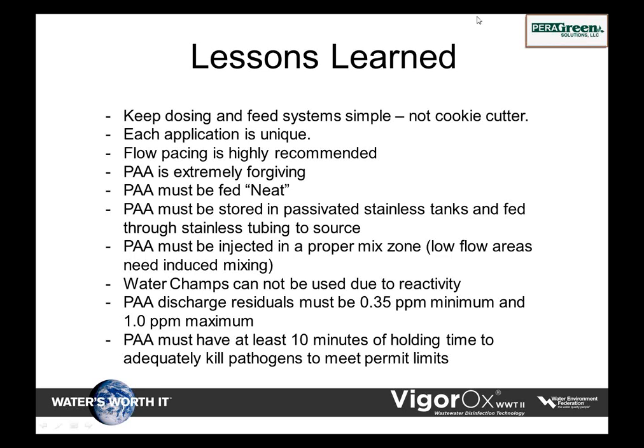But very simple systems. We applied it directly into the middle of that combined pipe. It was a 24-inch pipe that came down and took a 90-degree turn. We did dye tests to verify the flows that actually hit. We injected dye and tested it as soon as it hit the head wall, so we knew 5 seconds was the time frame at 7 mgd.